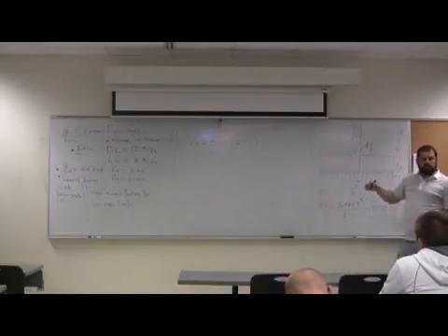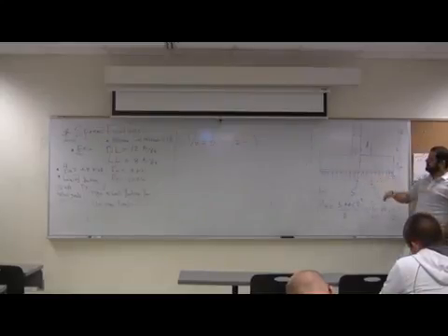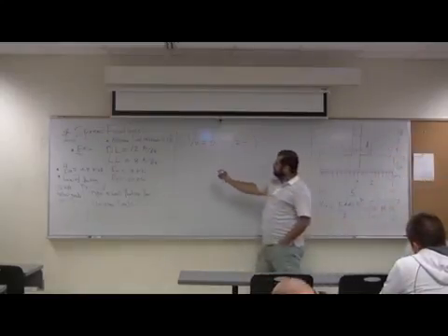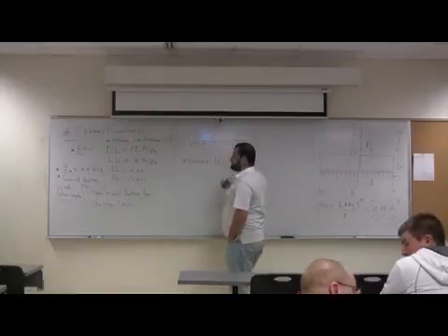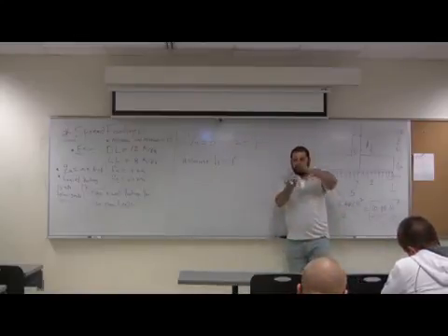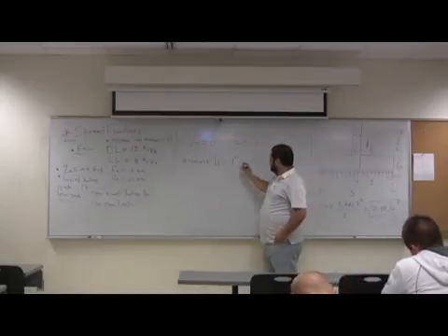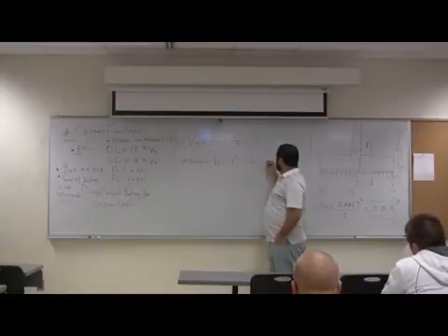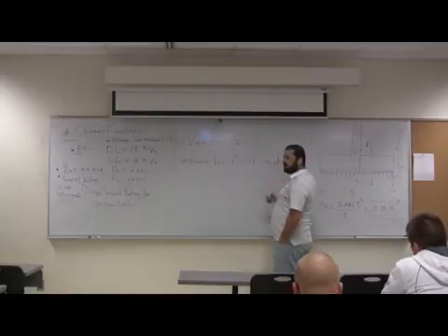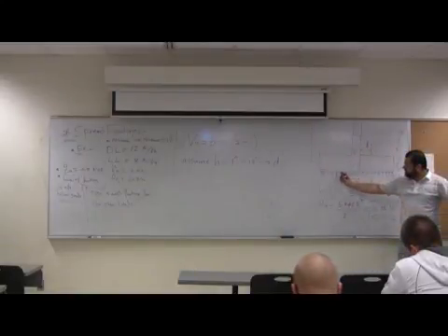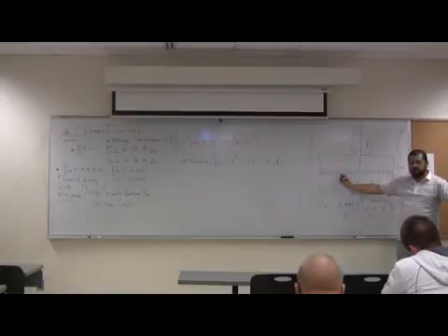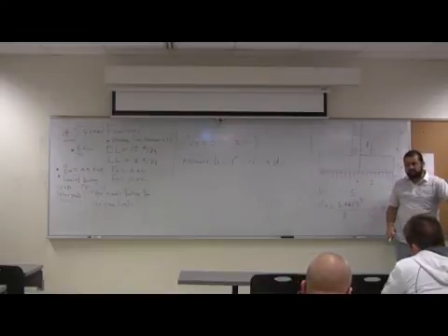If we assume H equals 1 foot, as I told you, this is a good start from experience with the wall footing, which is 12 inch. How much will this typically give you for D? Look at this, we said the cover above this bar is 3 inch, right? The cover above this bar is 3 inch. So how much do you think the cover to the center of that bar?